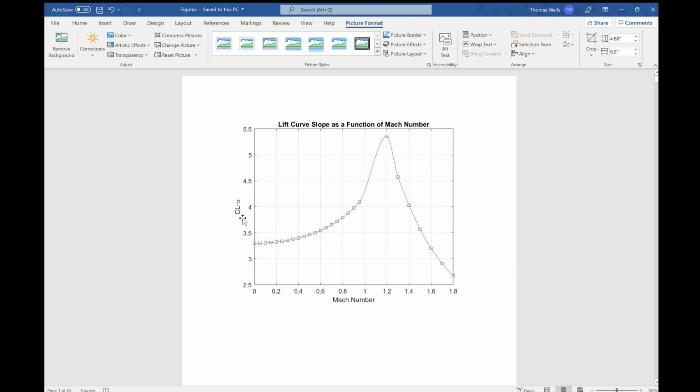And this will be valuable to look at what's the maximum CL value that is obtainable at any specific Mach number, because we know the limits of stall in the airfoil, depending on which airfoil we have, what alpha it is going to stall at. From there, we can determine based on this graph what our CL is. And we know that we are looking for fairly aggressive CL. And this is also, sorry to note, as a function of radians, not degrees.